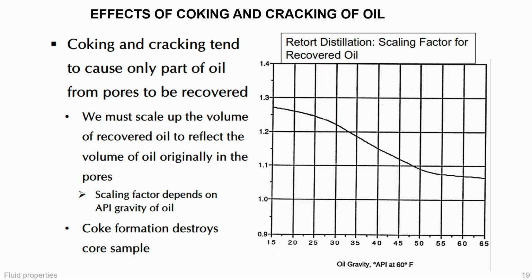Here the message is: at high temperature, crude oil composition can change. Cracking breaks long hydrocarbons into smaller ones, and coking leaves carbon residue. Both effects can distort saturation measurements. This is an excellent slide to teach students that measurement method matters as much as the measurement itself.